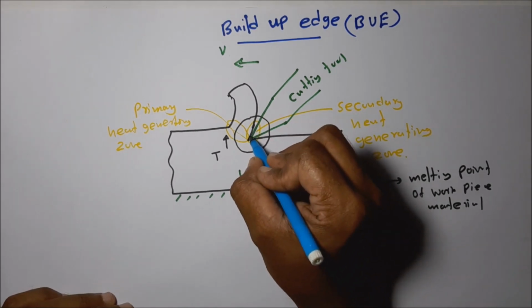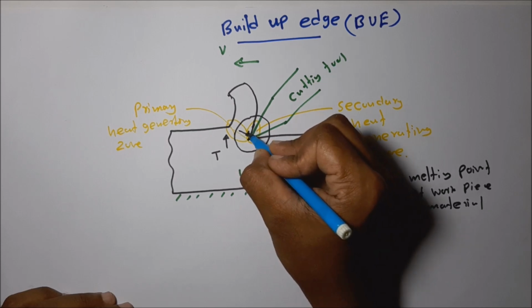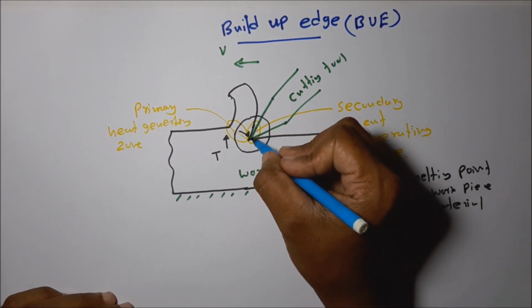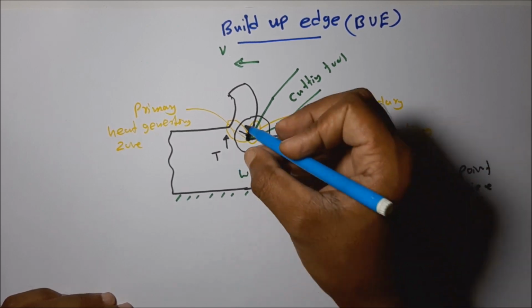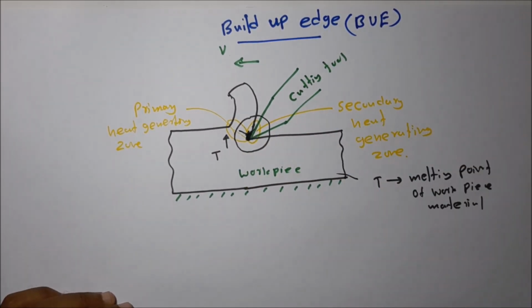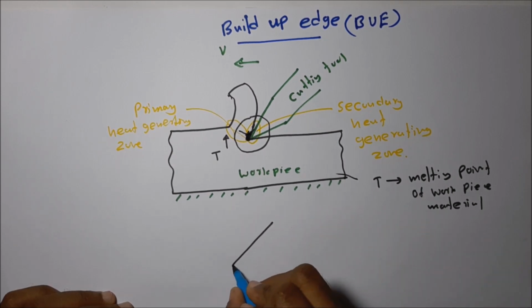Because of the high temperature and also the very high pressure acting on this tool, the material in this region melts and adheres to the tool tip. So I will draw the tool separately.